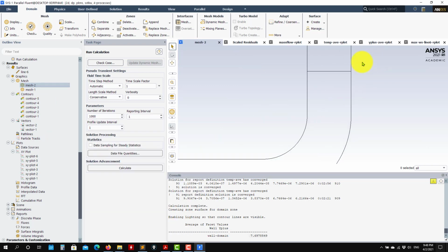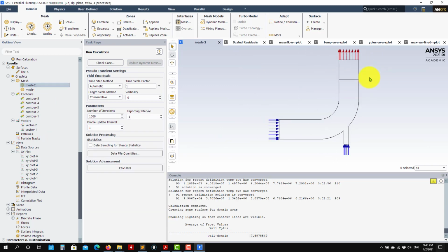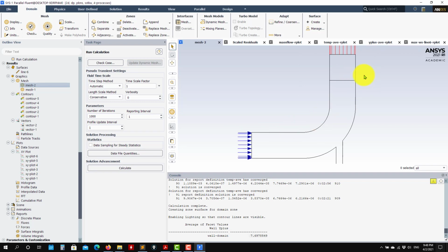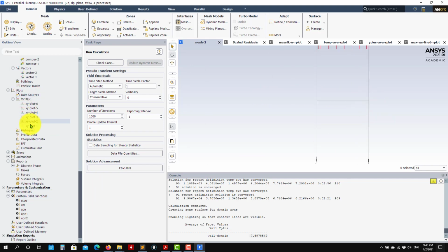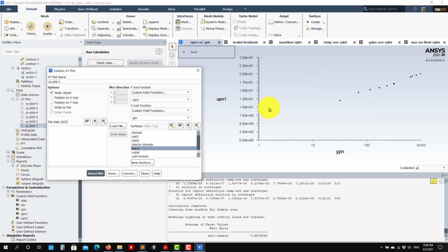To plot those profiles, remember, you need to pick a location in your domain, preferably a location where the flow is fully developed and attached. You sample the wall shear stresses, and then a line normal to the wall, sample the velocity. Remember, starting from this point, the coordinates are 0, 0. So it's the distance normal to the wall, so be careful when doing that. That's all you need to do for this plot. Then y plus, u plus, in logarithmic scales. You have it there.